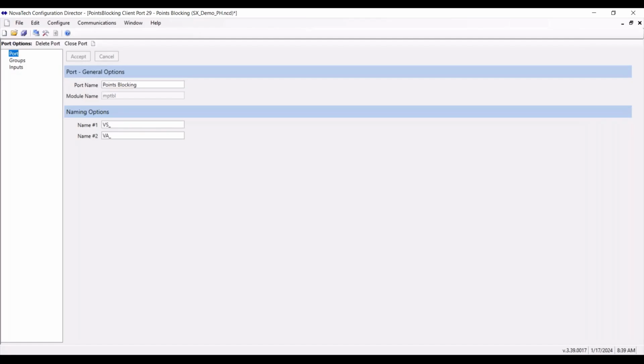In this way, you have one set that goes to your SCADA and one set that goes to your alarm, as an example. If you are doing commissioning or testing, these points can change internally at the substation, but SCADA won't see it or your alarms won't see it. So it's more for testing purposes. Let's say you're doing some testing, you don't want SCADA to be scared because they didn't know that you're doing testing and they see all these alarms coming in. So this is a way to create a separate set for each location. It could be multiple SCADA with separate sets, or a set of points that goes to your tile annunciator, for example.